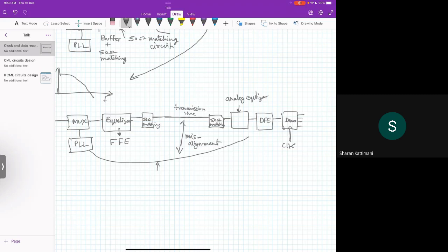Both will be in different environments, and because it is not possible to put them side by side, the PLL will be at some other corner of the circuit, so there is a possibility of a small change in phase, and that small change in phase results in badly recovered data.